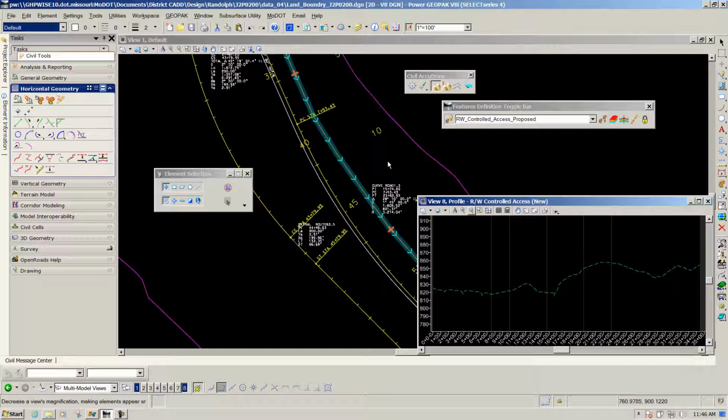The first part, when we did the plan graphic, again we did that because if you reference in that plan file with that plan graphic into your corridors file, you can target that plan graphic and make your template widen out or get narrower based on that location of the plan graphic. The only other thing you need to do once you have that plan file referenced in, you have to select that edge of pavement line and make it a corridor reference. So with that, we are now finished with our first exercise in Chapter 4.